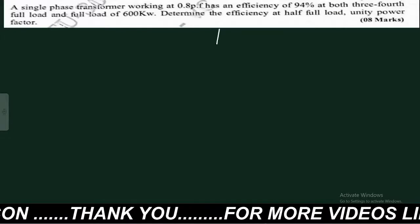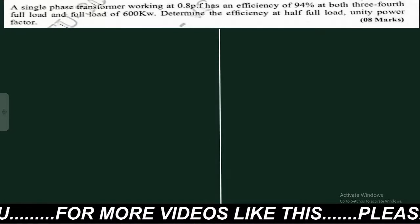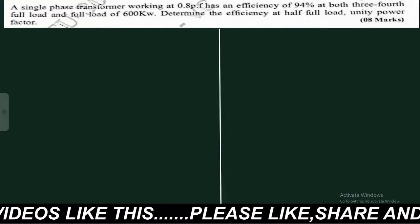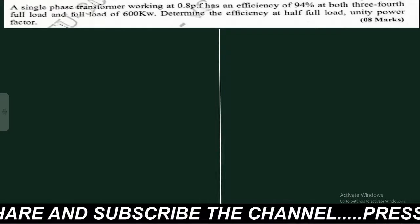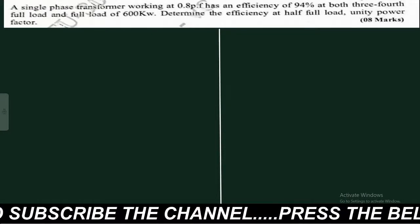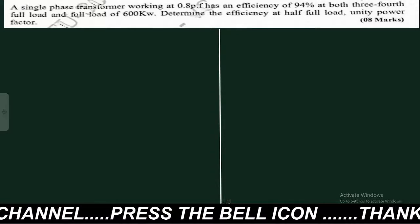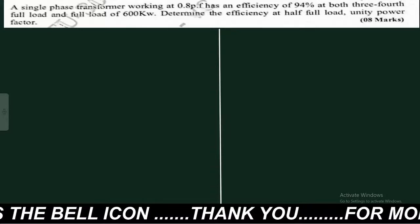Today we are going to see the questions given in the third and fourth modules. We will continue with questions 3, 4 and 5 in this video. A single phase transformer working at 0.8 power factor has an efficiency of 94% at both 3/4 full load and full load of 600 kilowatts. Determine the efficiency at half full load, unity power factor.